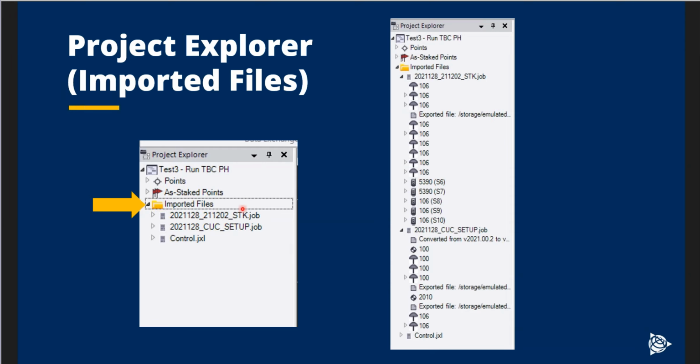We looked at imported files and drilling down through there. You know, this example here, this is a base station, and this file needed this point to create this vector data from the GPS down below. However, we get it here first. That's why bringing in this JXL is important, because now we could remove this if this is a bad value. In this case, it's not, but this is where we could remove that in our imported file section.